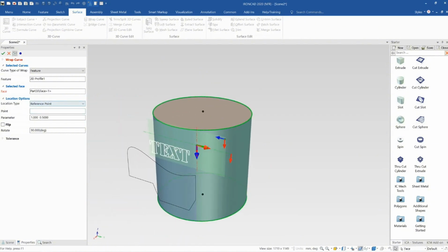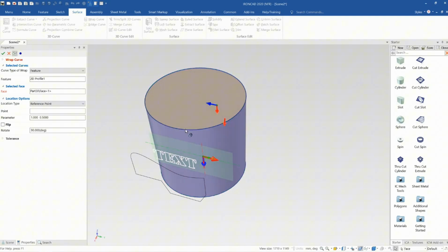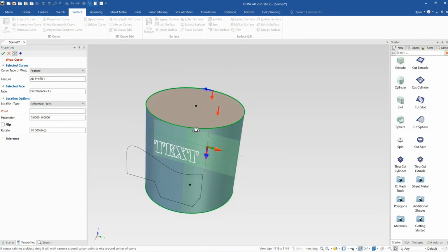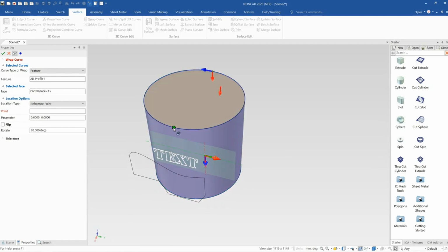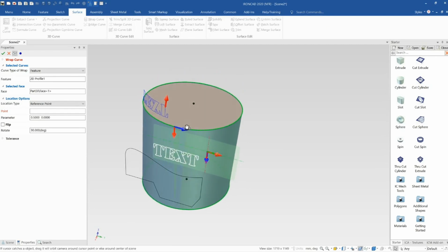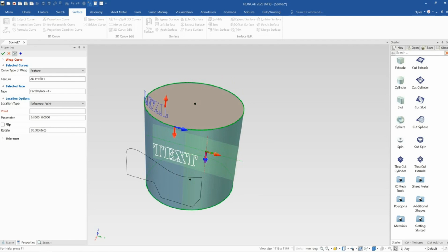But if you do want to use it, you basically just select a point, and then you can define everything in relation to that point. So as long as you select a point on the surface, you can then go from there. So if I just find a point to select for us somewhere along this surface, I need to select into the point field first. And I'll select on a point like that, and that's now our reference point, and everything moves based on that point. So I could select the front up here as well, and then we can define everything relevant to that point. So again, I'll change this to 270, flip that over, and so on.